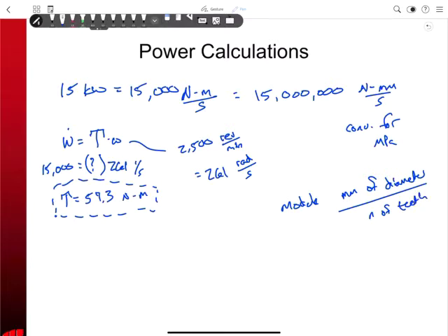So I know I've got 14 teeth, so 14 teeth times 5 millimeters per tooth. And so then I find out that the diameter of my gear, what's 14 times 5, is that 50, 70? 70 millimeters, right, which equals 0.07 meters, right? So I have not yet decided what my unit system should be, so I'm kind of mixing it up. 0.07 meters, and then so now I can figure out my F tan here.